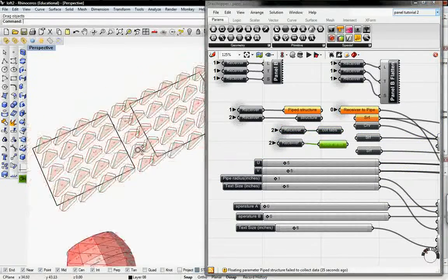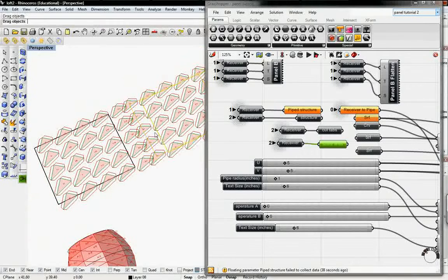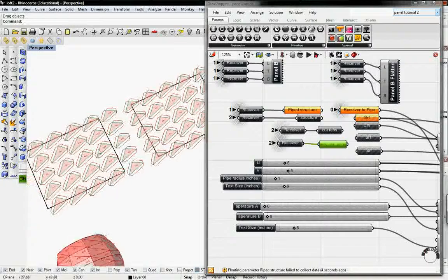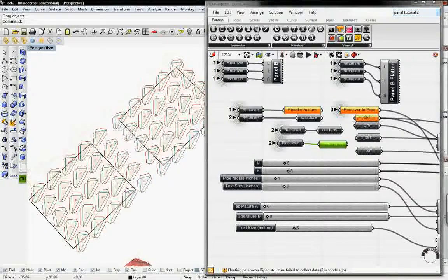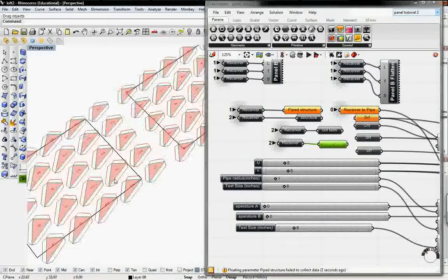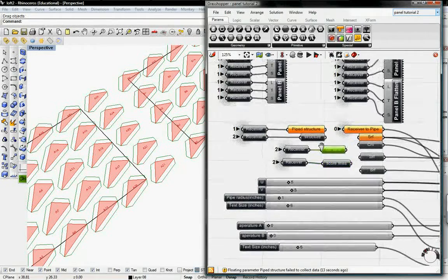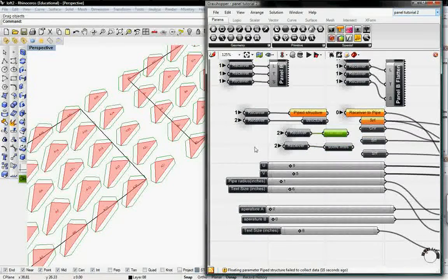And then you can move this tab out of the way here, so you guys can prefab or cut this with the laser cutter a lot easier by telling the layers which layers to score and which layers are cut. And then that's how you create tabs in Grasshopper.